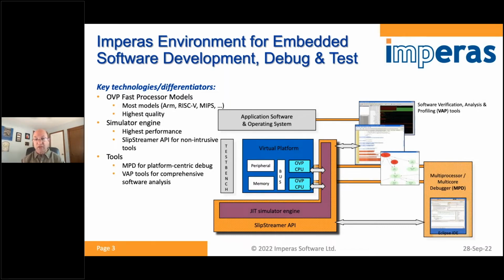And then we also have MPD, our multiprocessor debugger, which provides not only for source line debug of the processor, but also supports heterogeneous platforms and also supports introspection of the peripherals so that you can do driver peripheral co-debug. So that's the software side of things.